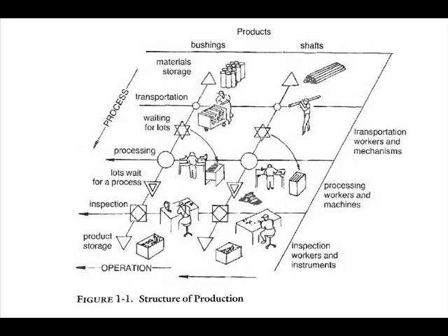The four conceptual stages of SMED are identified: first, IED and OED are not distinguished; then, IED and OED are distinguished; next, IED is converted to OED; and finally, all aspects of the setup are streamlined. In Chapter 4, practical techniques corresponding to these four stages are described. Significant improvements in setup time can be achieved at each stage of setup.